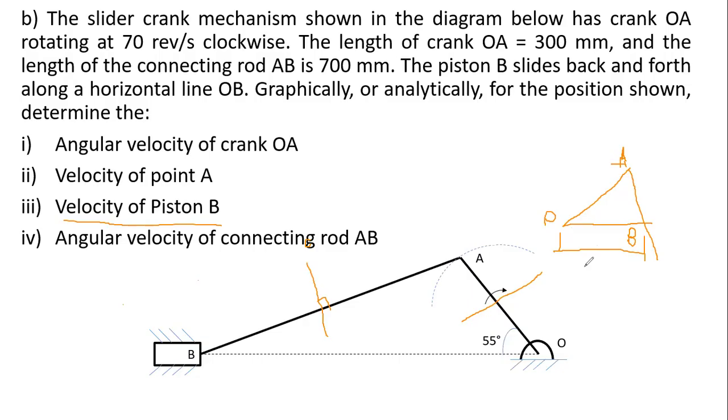Then I refer back to the original scale, where 5 centimeters represents the velocity of OA, which was 131, and we calculate backwards to find what this measured distance represents. So we're interpreting the velocity from the velocity diagram we've drawn. In the graphical method, things are as simple as that, as long as you ensure that you've carried your instruments.